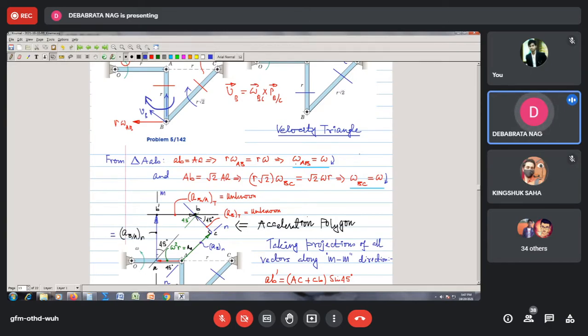Now its magnitude should be equal to omega AB square into AB. Which tantamounts to saying that it is equal to R omega square, because AB is R, and omega AB is omega, which we have just now found. So it is omega square R. So I erase these two things and simply write it to be equal to omega square R. Why is it so? I think you have understood. So this is equal to omega square multiplied by R.